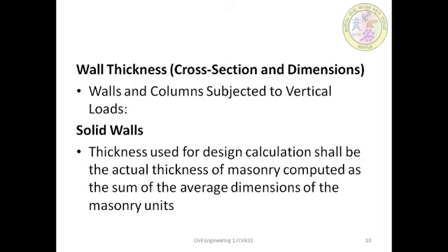In case of plaster work, raking is intended to provide a key for bonding the plaster with the background. Strictly speaking, the thickness of the masonry for the purpose of design is the actual thickness less the depth of raking.